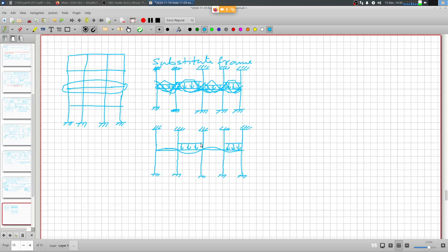And this will have an entirely different bending moment distribution, because these two joints will obviously try to rotate and have a hogging moment, kind of deformation in this unloaded span, and similarly this unloaded span will also have hogging moment. And this has a critical combination on the loads that are coming onto the structure.